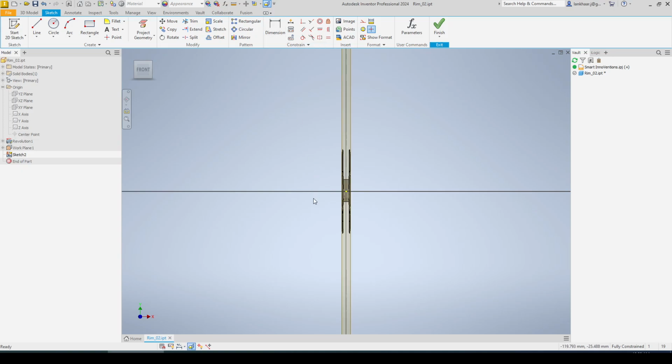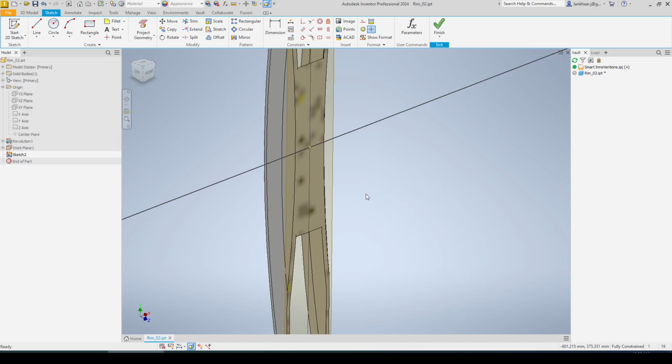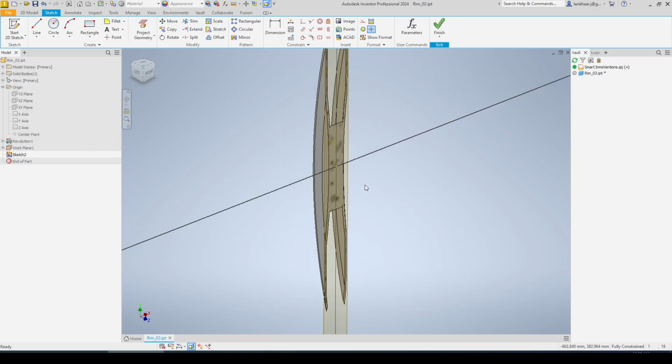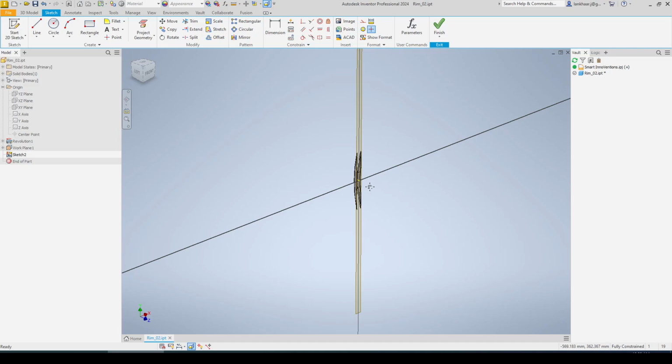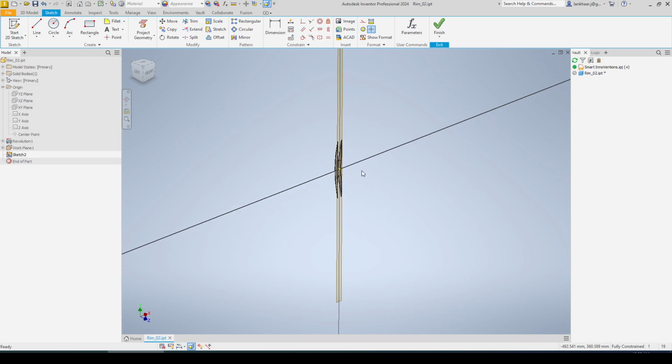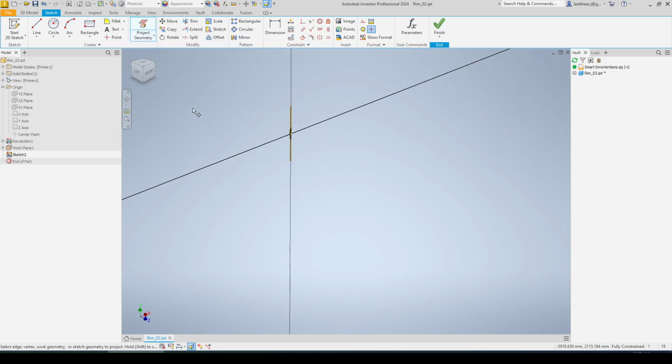So now, when I turn this thing a little bit, I only have this view, which is perfect because I'm not bothered by the rest. Okay. So, to make this hole in the middle of the two planes and in the middle of the rim, I'll use a trick, and it's called project geometry. That's this one. So I'm going to project, and the dot should be in the middle, but we're not sure of it. In the previous one it didn't work out.